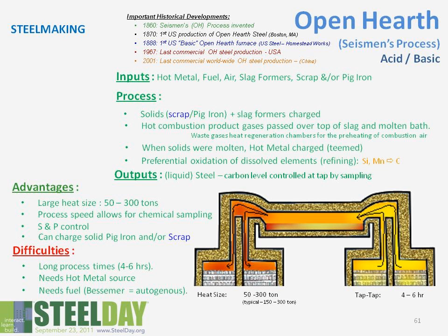Okay, other steelmaking processes. At around the same period as Bessemer came out, a competing process known as the Siemens or open hearth process was developed. This used scrap and pig iron, initially charged to the furnace. Again, a reverberatory furnace, so heat was impinged upon the solid to melt it. After a period of time, hot metal was added.